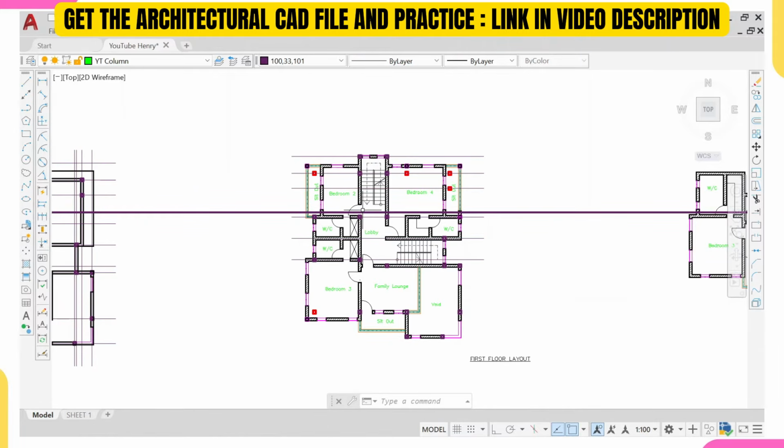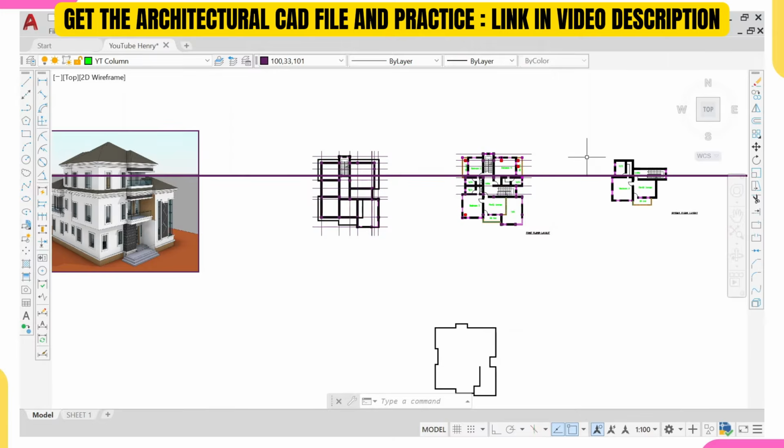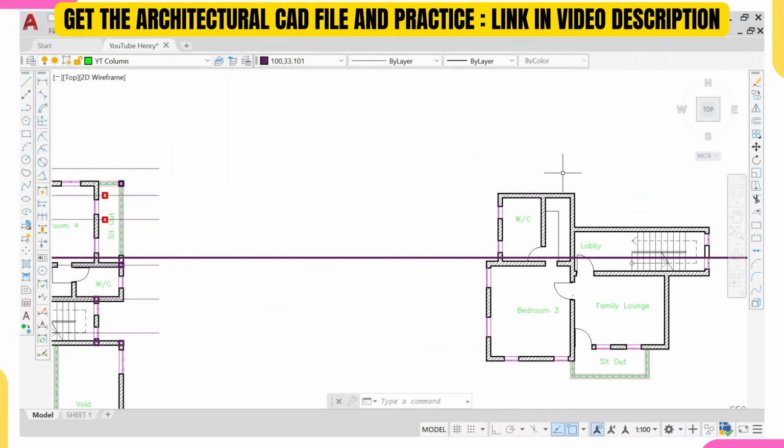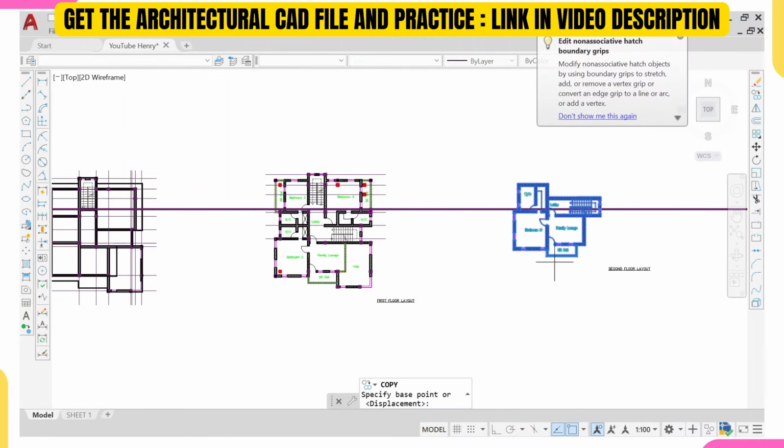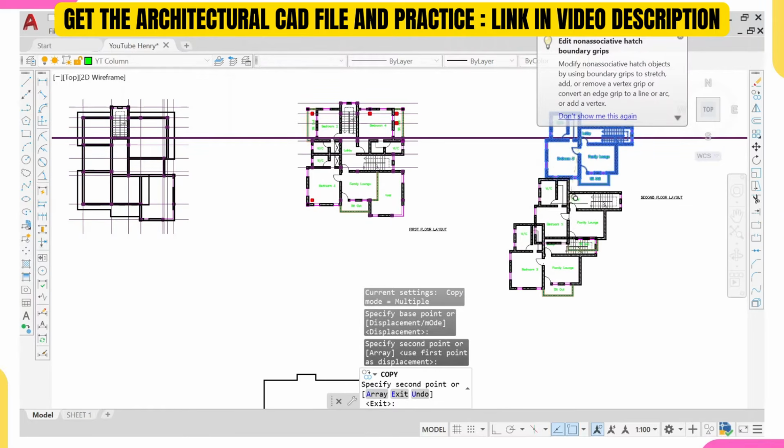Then plus the depth of your slab, making it 450, because 300 plus 150, which is the depth of your slab, makes it 450. So these ones that are not really carrying anything again will be 300, because they are no longer carrying any slab. So what I'll do now is let me just do CO enter, and let me keep this in at this point.